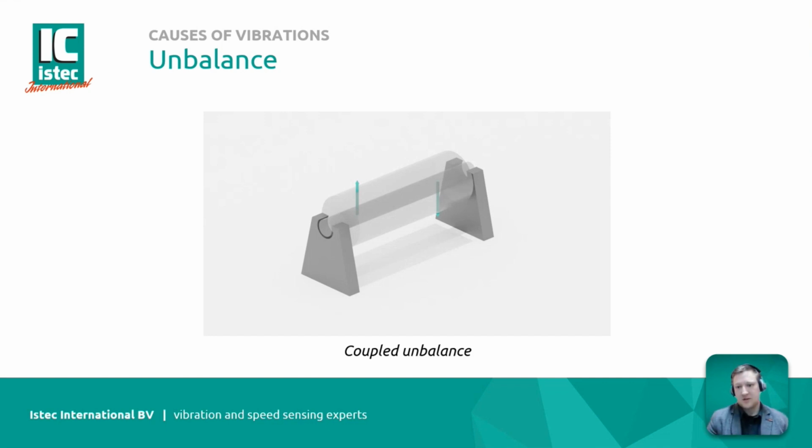And dynamic unbalance, which is most commonly seen, is a combination of both static and couple unbalances. In this picture it's really simplified, but you can imagine that when a gas turbine rotor is built up, it consists of discs, blades, and tie rods. It's a complex build-up, so all these components will have their own unbalance vectors, which will all come together as one unbalance source.